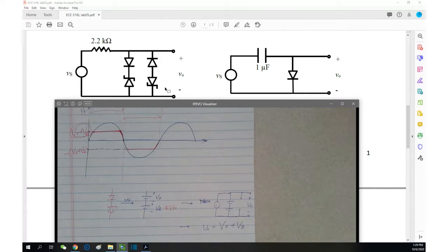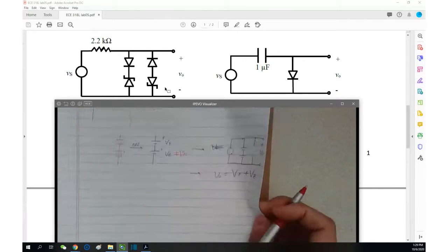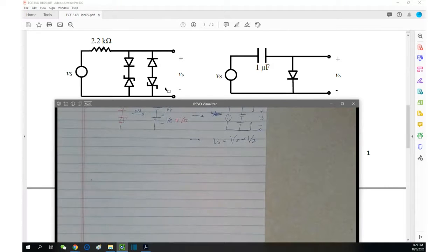And the next circuit is the clamper circuit. The clamper circuit is not chopping. This capacitor clamper circuit is not doing any chopping. It's just clamping, or say shifting, your source. How to shift? This is a little bit tricky to understand, even though the circuit is very easy, right? One diode, one capacitor, one AC source. However, it's not very easy to understand.